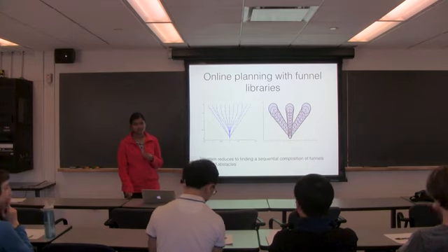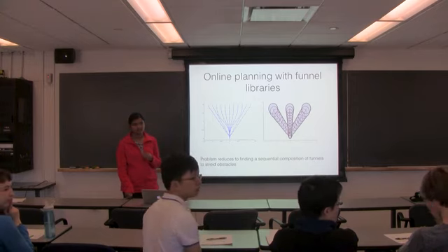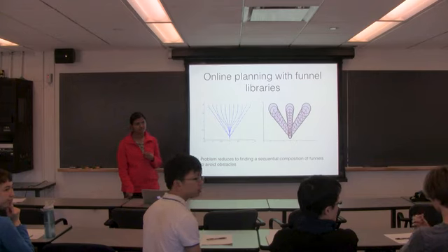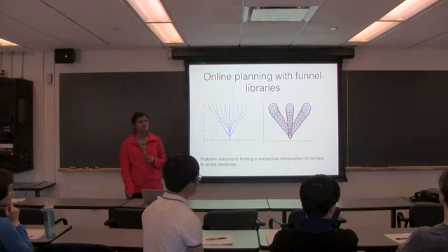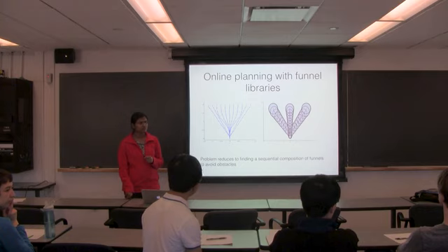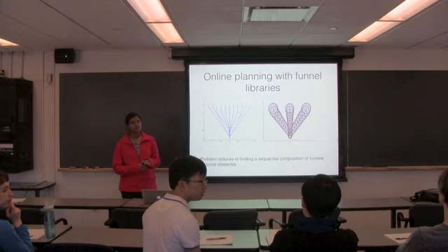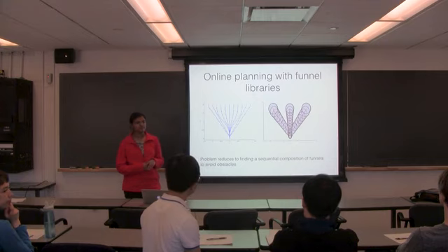Yeah, I think what he just said is the point of the funnels: they provide a control policy. The actual reference trajectory that you have on the left is the motion planning. But with the funnels, you get a control policy, because when you start executing the motion plan, there's always going to be a disturbance. So you want a control policy that keeps you on that trajectory.